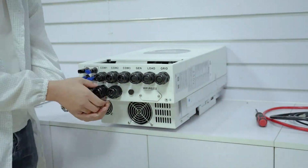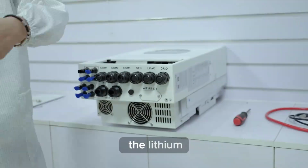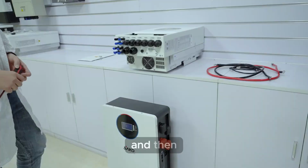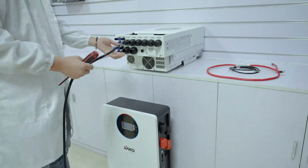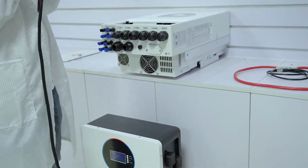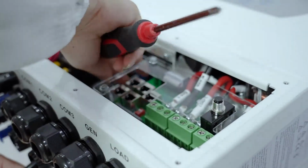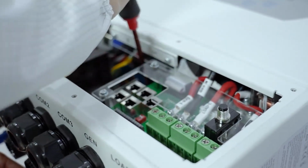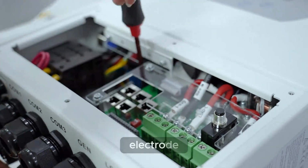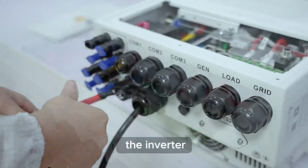Step 2. Use the battery connection line to connect the positive battery pole of the lithium battery to the positive battery pole on the inverter, and then the lithium battery negative electrode is connected to the negative battery electrode of the inverter.